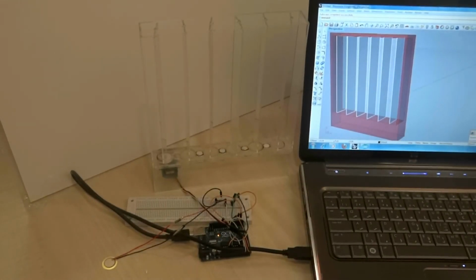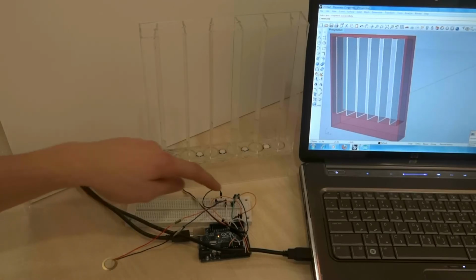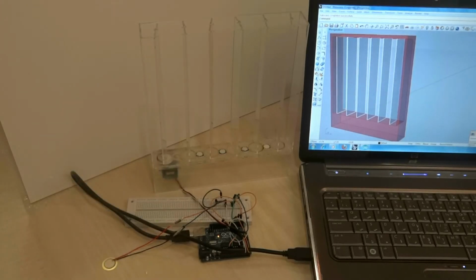So I've shown the digital and physical model being controlled by Grasshopper and Firefly. Now I'll control both models via real-time data and a pressure sensor, which when calibrated to a very sensitive level can pick up changes in pressure, which obviously vary with wind speed. So I've added this piezo pressure sensor and a 1 megaohm resistor to the breadboard, and this sensor has been connected to Firefly via a read component, which ultimately sends signals to the servo. It's calibrated so when the wind speeds reach 8 meters per second or more, the panels will close.